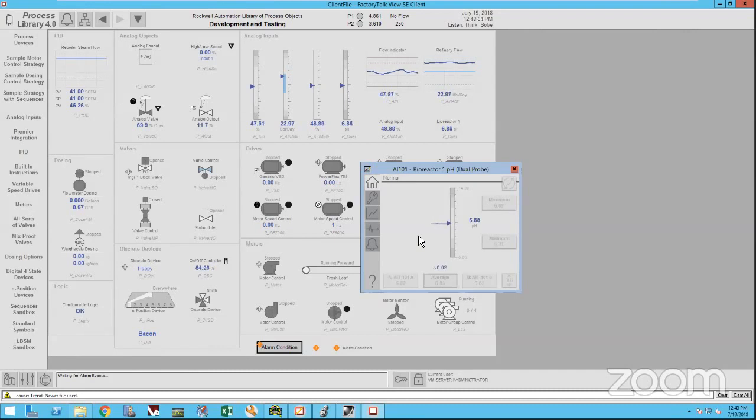What you'll see here, as I mentioned, so I just opened this guy up. I'm now getting a little trace line. So as my value in the analog goes up and down, if I have that open, I'm now seeing what that variation is. The different shading of gray here are my deadbands for my alarm. As soon as that alarm hits one of those shaded deadbands, I now go into alarm, that changes color to yellow or red based on my severity level that I assign. I now get an alarm, I can acknowledge back to the controller, it's in a handshake back and forth. If I'm looking at this, this is also where I would set my deadbands, I would be able to set my threshold levels, my trends, so if there's anything that I need to change there.